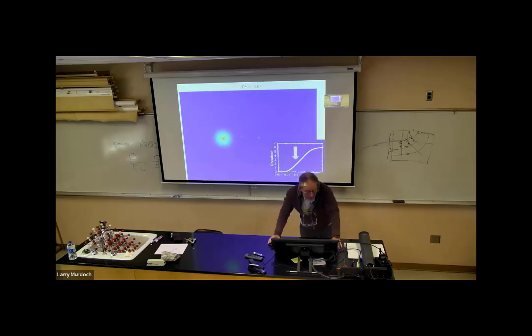All right, so we continue to pump. This radius of influence expands. This is the cone of depression here. See how those contours are kind of blocky because of how the contour is drawn, but these should be circular. You can see how the spacing decreases as you approach the well.